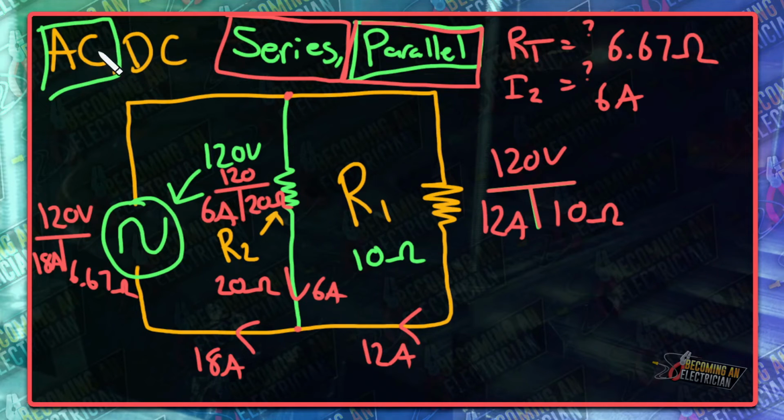But in the real world, like I was saying, we as electricians are using AC, okay? And we are also using parallel for all our circuits. Whenever we are wiring our lights, whenever we are running 14/2 to all our plugs and to all our lights, all that stuff is in parallel and it's all in AC. Again, when it comes to a resistor, this is a purely resistive load, such as a baseboard heater and an incandescent light bulb. Therefore, this theory applies to this.